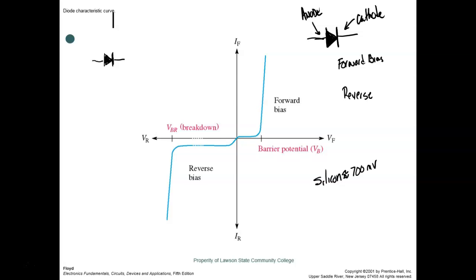If I came up here and measured a positive on the cathode and a negative on the anode, I'd throw my diode away. It's usually in respect to. So if this guy right here is this, then this guy's got to be bigger, right? You understand? So the cathode has to be made negative in respect to the anode.